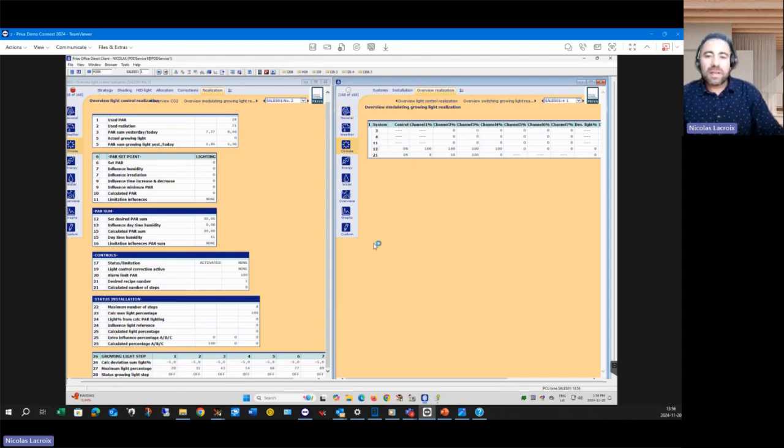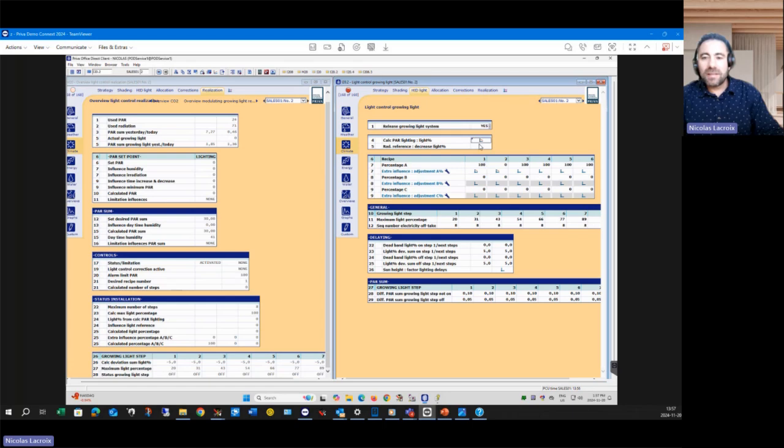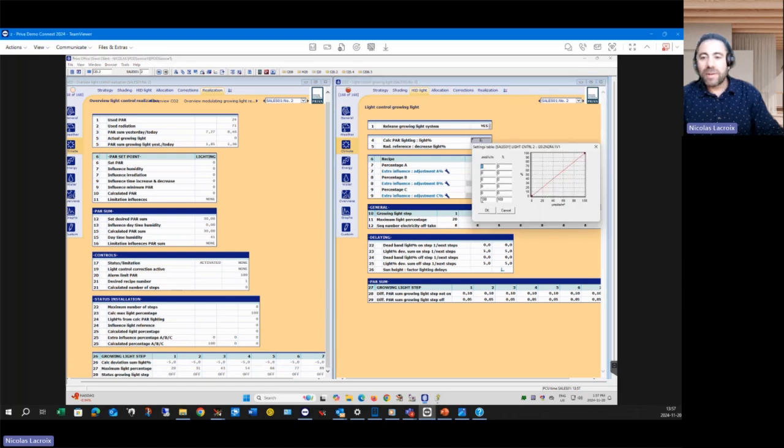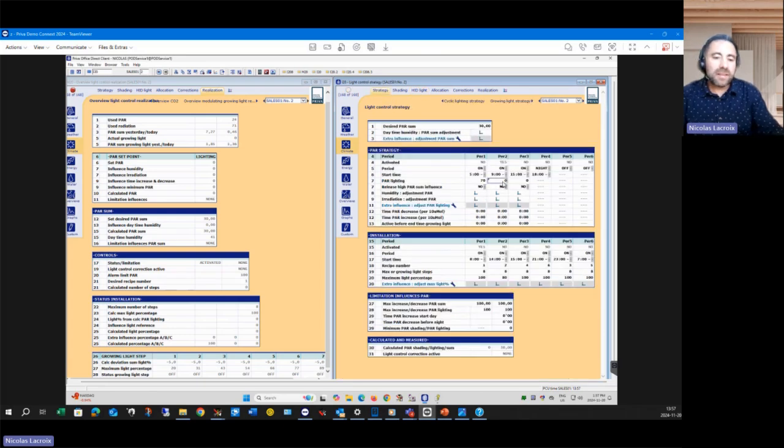So if I go here now, I will put the set point at, remember, my table is set to make it easy. So my table is set 100 micromole equal 100%. So the number of micromole that I set here is basically the same as the percentage. Okay, so now I will set 15%. You see that my minimum is set at 20 here.